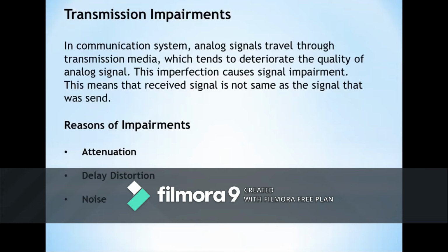In practice, crosstalk can be experienced while using a telephone. We can hear another conversation due to crosstalk. It can occur due to electrical coupling between nearby twisted pairs, or sometimes even in coaxial cable. Typically, the magnitude of crosstalk is almost the same as the thermal noise.